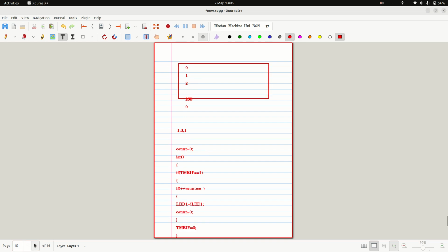So here can I write 20,000? Yes. Can we write 20,000 here? So according to the calculation, after every 250 ticks interrupt gets generated, after 20,000 times you visit the ISR, we can toggle LED. So this is what disadvantage, isn't it?